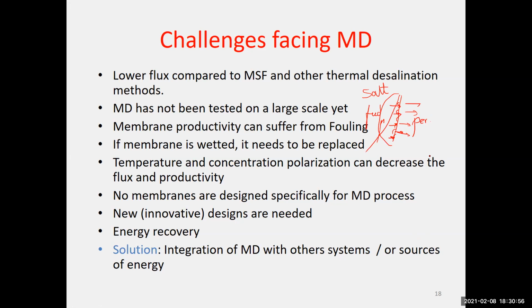Is there a solution for it? Yeah, there are techniques for the concentration polarization. One of them is basically doing a backwash for the membranes. If it's an RO system, we just admit the water to be passing in the opposite direction so that it pushes the salt away from the surface. Can we do that with vapor? Yes, why not? It can be done in a way that you try somehow to clean the feed side.